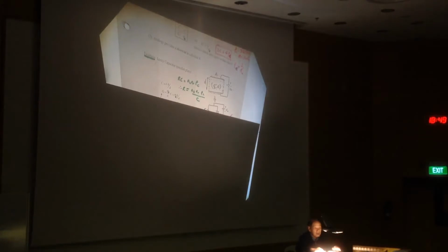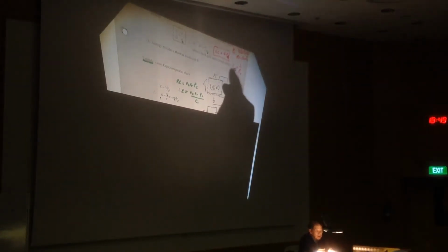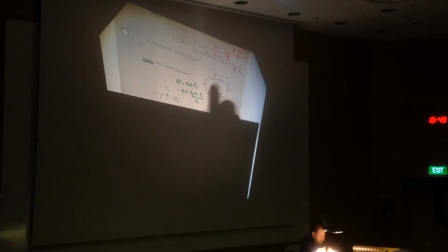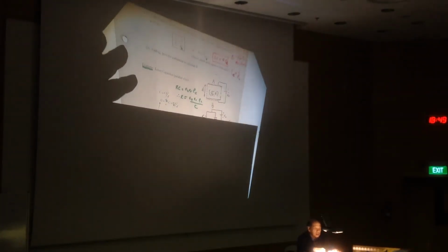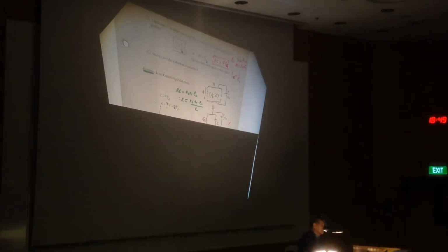So when you connect a source of DC voltage across it, first the charges accumulate. After a while the charging finishes, but there will be a small current flowing. A very small current due to the small sigma C. So this is what is called a lossy capacitor. And all capacitors are lossy. There is no perfect capacitor.